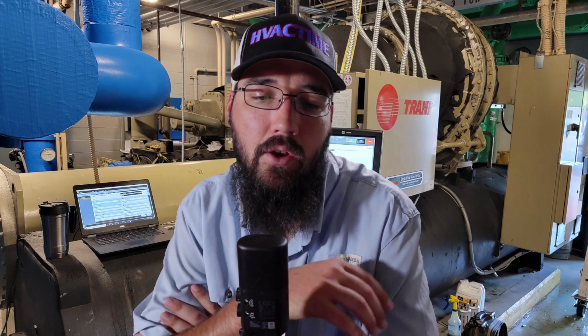But the compressor gets controlled based off of leaving water. So as we need to cool the water down more, the compressor will ramp up, and that will influence where our levels are in the heat exchangers, and then the metering valves will adjust accordingly to get that level back to whatever set point it was meant to be at. That's overall how we balance the machine and maintain a stable level and flow during operation, instead of trying to rely strictly on, say, superheats, which are very subjective.